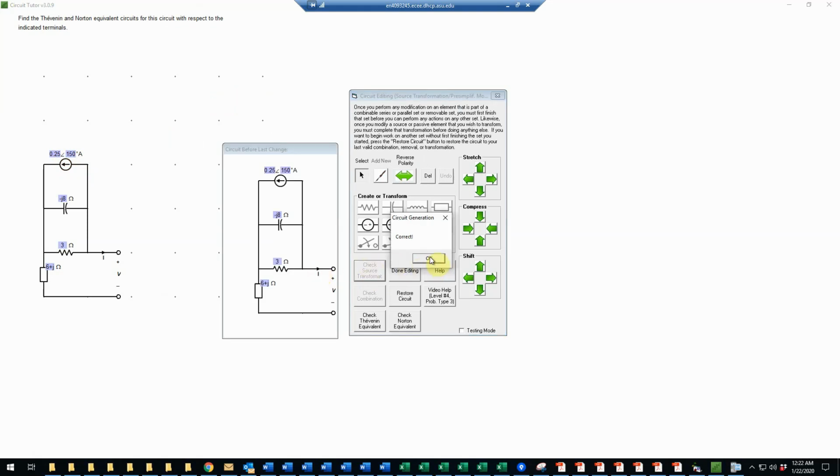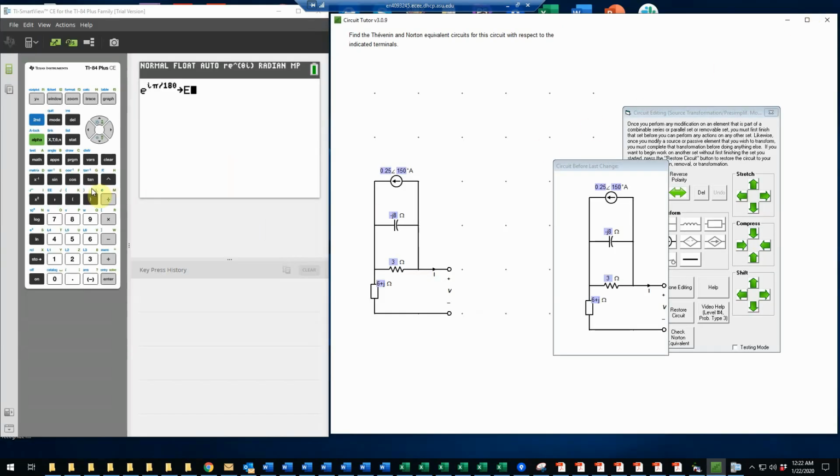And that is correct. And now I have two impedances that are in parallel. So I can combine those by using the product over sum formula. So that would basically be negative 24j divided by 3 minus j8. Well, I can't do that in my head, so let's go get the calculator. And I'm using a TI-83/84, well actually it's an 84 Plus emulator to be precise. Now I'm going to want an impedance, so I'm going to want that in rectangular form.